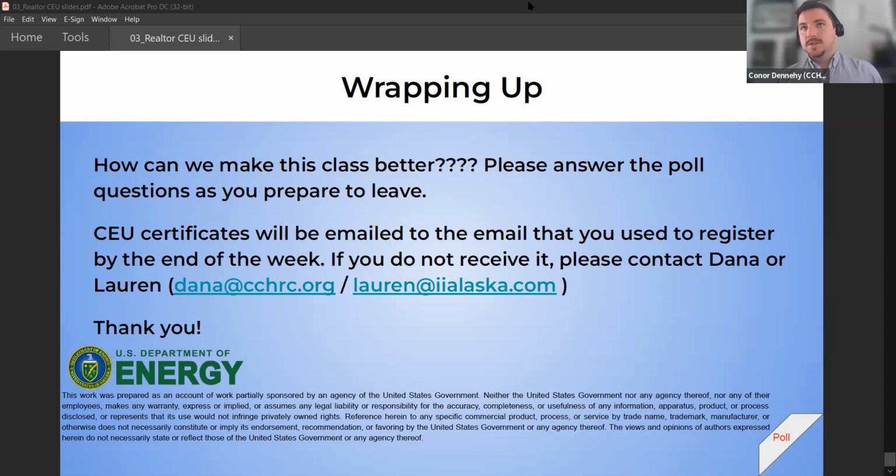Yeah, that's a great question. Ductless mini splits are pretty low maintenance. If you think about heating appliances in general, but even just heat pumps in general, ductless skew towards the low maintenance side. They have a little filter on them, mostly to protect the fan rather than filter the air. So if the homeowner keeps that clean, that's most of their maintenance on the inside. On the outside, maintenance would be making sure snow doesn't pile up around it and rain isn't filling it up. When they defrost in the winter, they might get some icicles, so they might want to go out there and knock them off.